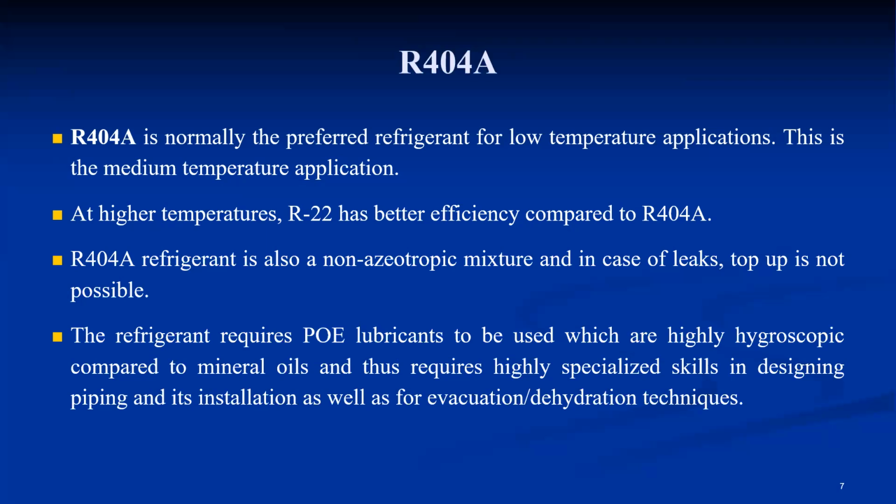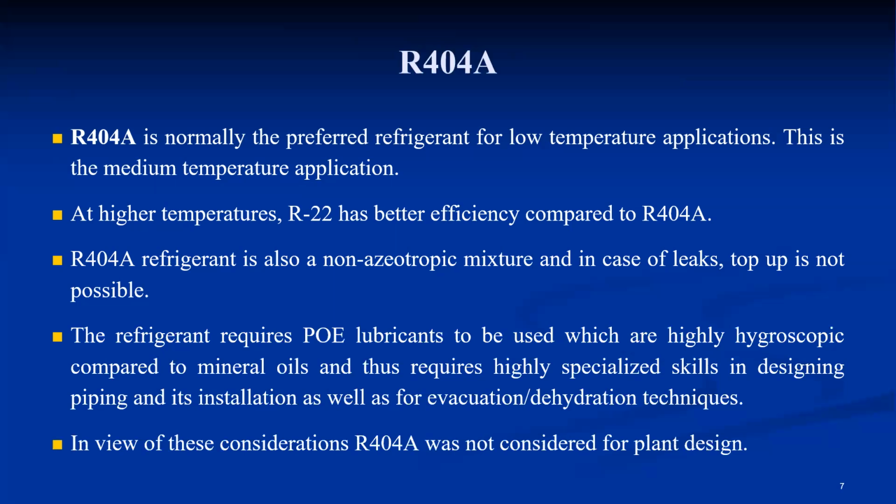This requires highly specialized skills in the design of piping and installation, as well as for evacuation and dehydration techniques. So that is the problem associated with this refrigerant, because POE oil is highly hygroscopic. So high level evacuation is required, and the time of charging is a slightly complicated process. These are the four drawbacks of R404A. And in view of these considerations, 404A was not considered for the plant design.